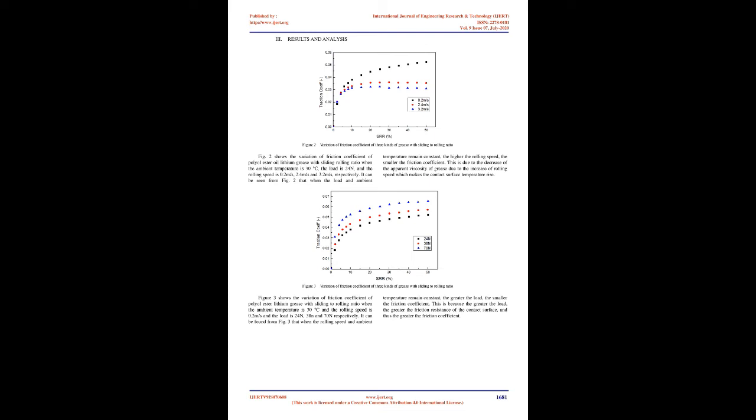In order to ensure that the contact area is always fully supplied with grease, a polyester device is placed on the track of the disc, which can return the grease on both sides of the track back to the track. The principle is that the contact part between the polyester and the rail is a trumpet type with large ends and small middle. The grease on both sides of the rail is gathered at the large bell mouth and squeezed into the track with rotation.